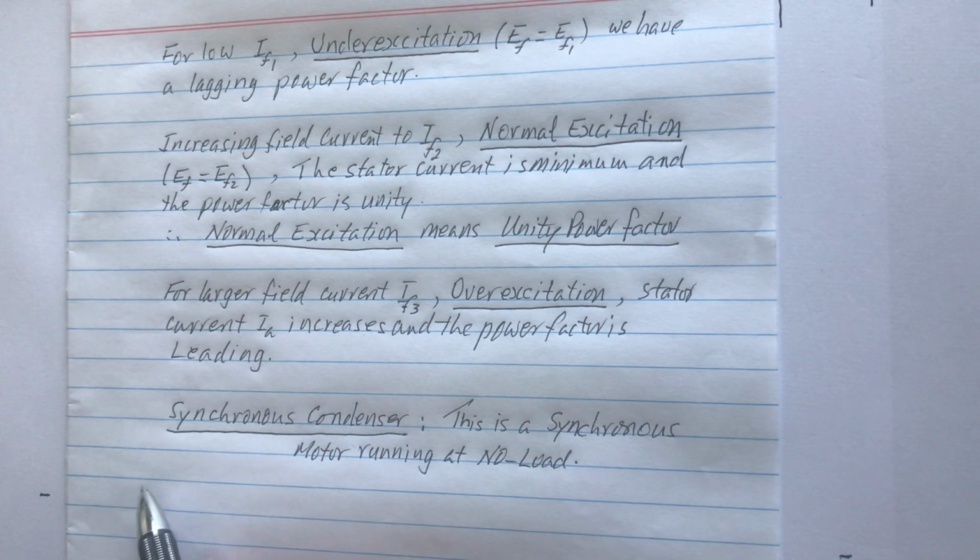For example, you start from Aqaba with 132 kilovolt line voltage. When you reach Amman, it will lose about 10% or more of its value. So you use a synchronous condenser, which acts like a capacitor, to bring this voltage back to its original value.